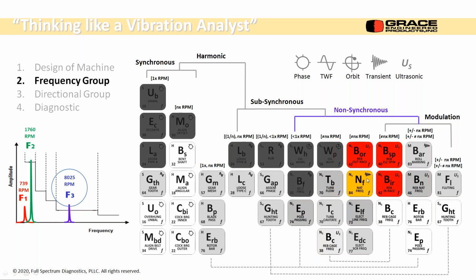One, like always, is the natural frequency problem. The other 3 are the outer race defect, the ball spin, and the inner race defect on the rolling element bearing in position 4 on our fan. So what do we do? We look for directional type help. Look in there, nothing happened. So it looks like it's probably all a radial problem, but we still have to check out the natural frequency for sure.